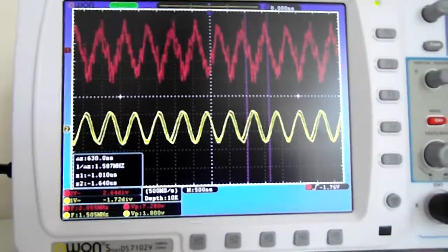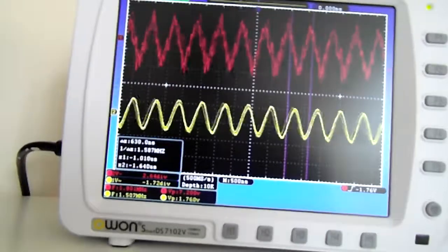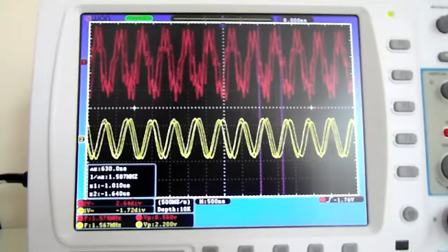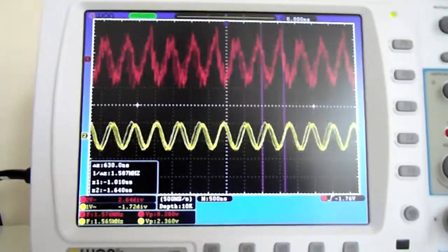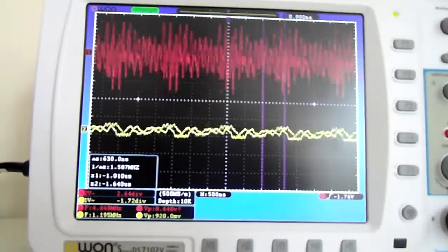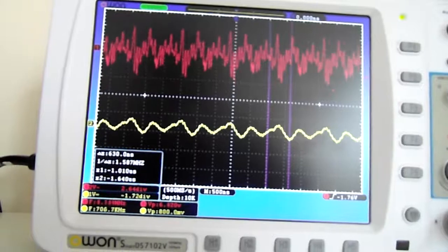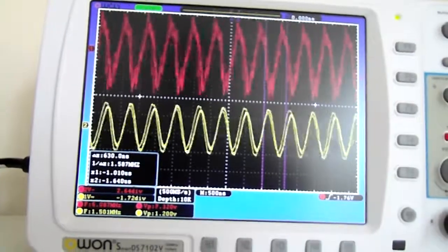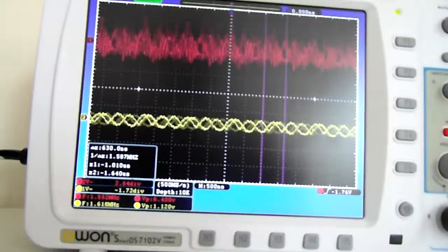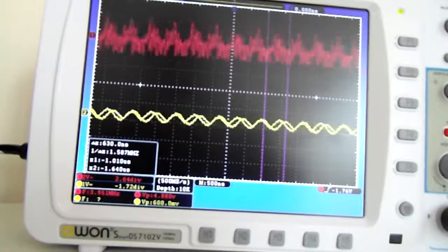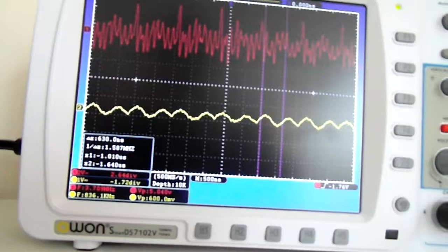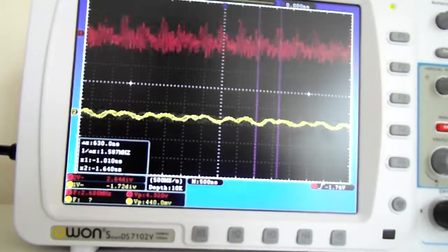And this looks like a ferroresonance. Around here is 500. The yellow is radiation, and the red is a ferroresonance, which is the copper bar voltage. I'm going up the frequency now. It's 730. So it's always the ferroresonance appears from time to time. Now the radiation and ferroresonance both are quiet at 800 kilohertz. And then I'm going up.